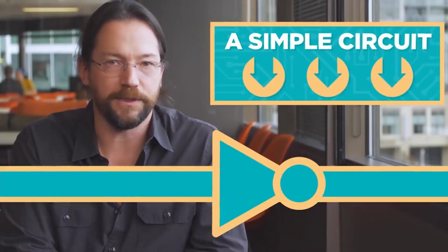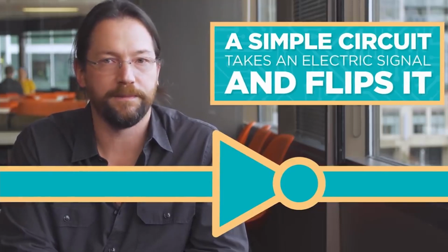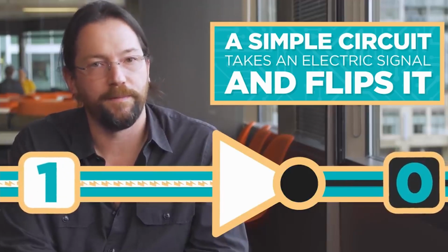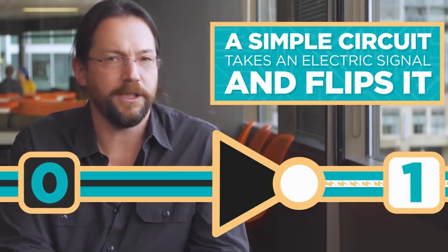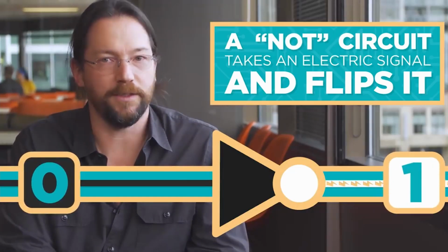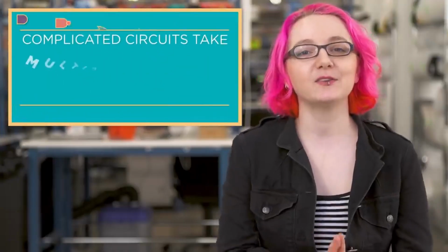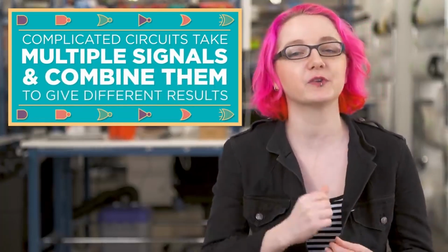Let's take a closer look at how circuits can modify and process information that's represented in ones and zeros. This is an incredibly simple circuit. It takes an electrical signal, on or off, and it flips it. So if the signal you give it is a 1, the circuit gives you a 0. And if you give the circuit a 0, it gives you a 1. The signal that goes in is not the same as the signal that comes out, and so we call this circuit NOT.